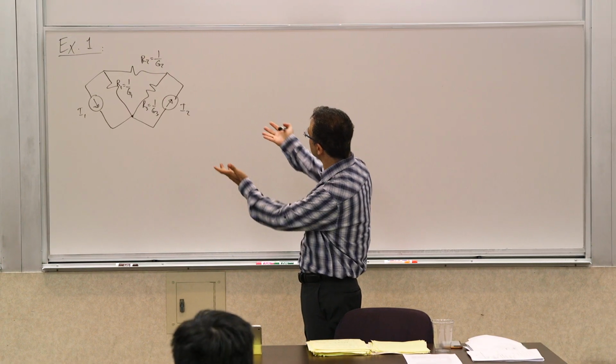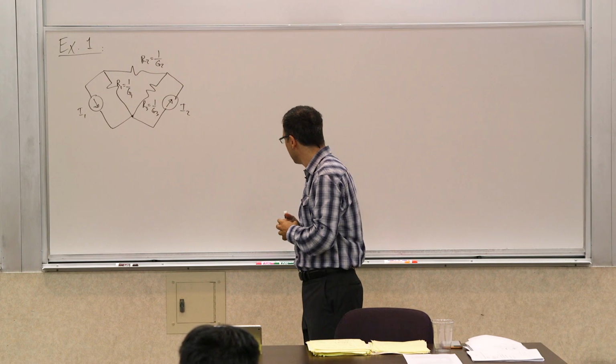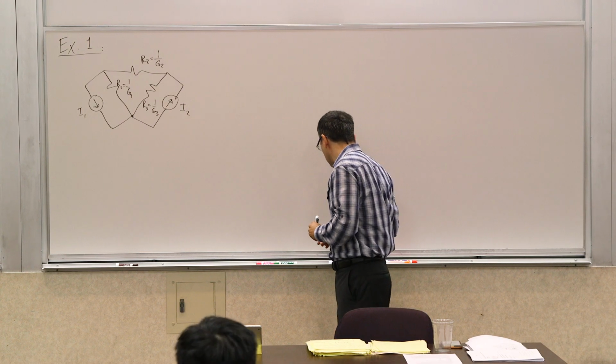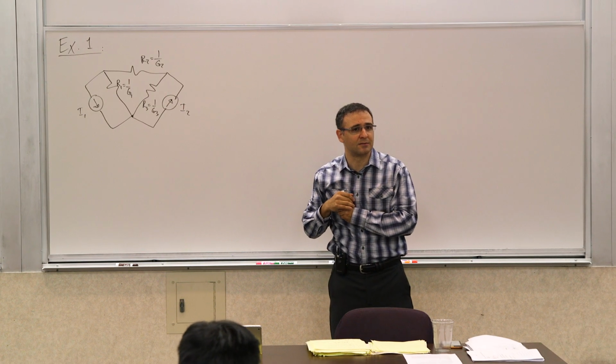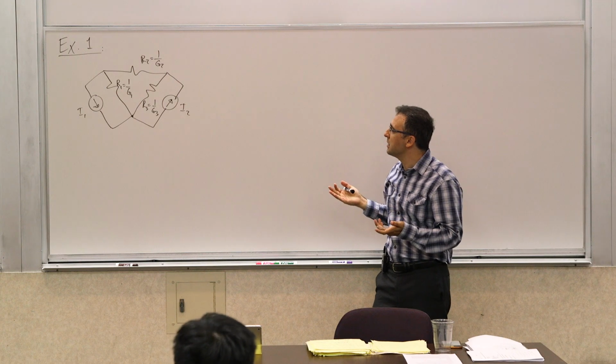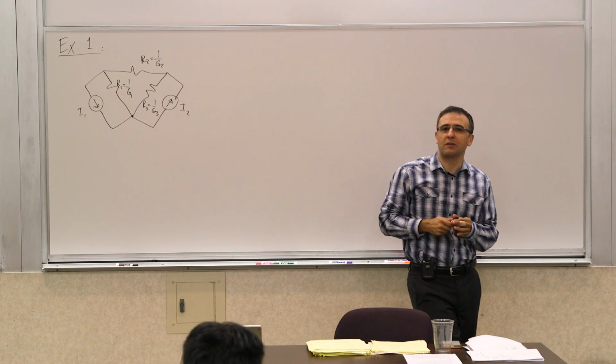So step one. So this is the circuit. Let's say this is the circuit. Before I apply anything to this, what's the first step if I were to do nodal analysis? Define a ground, right? So which node would you define as ground?